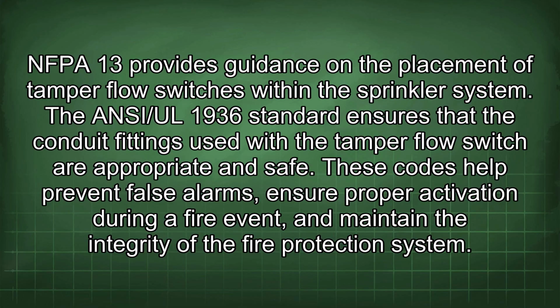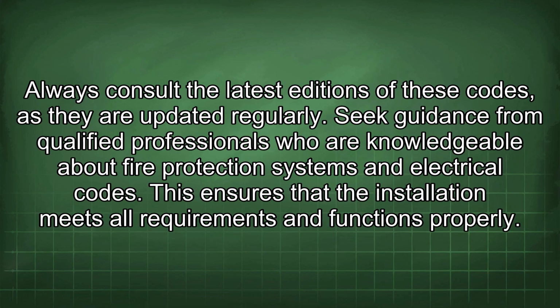The ANSI/UL 1936 standard ensures that the conduit fittings used with the Tamper flow switch are appropriate and safe. These codes help prevent false alarms, ensure proper activation during a fire event, and maintain the integrity of the fire protection system. Always consult the latest editions of these codes, as they are updated regularly.